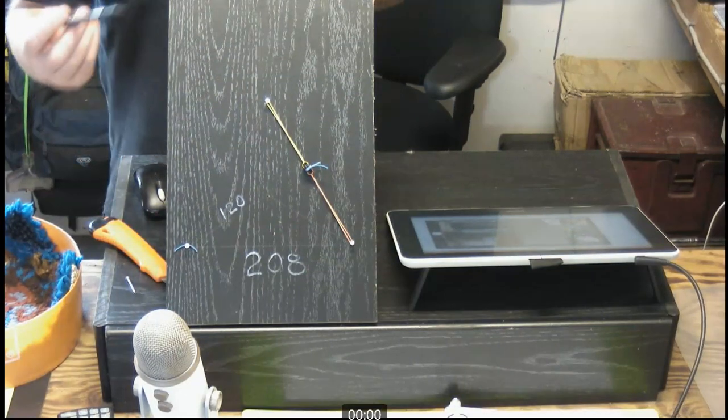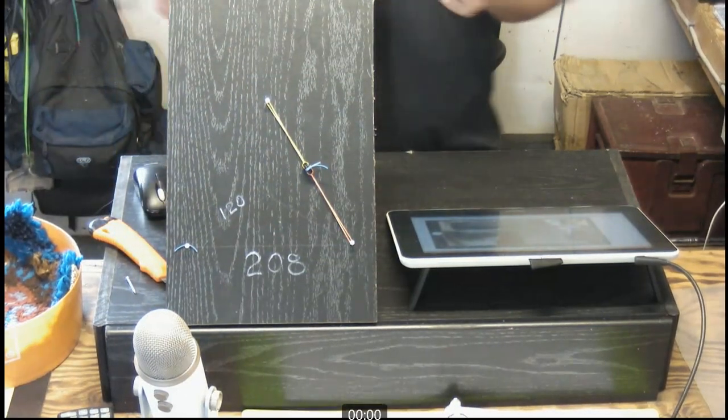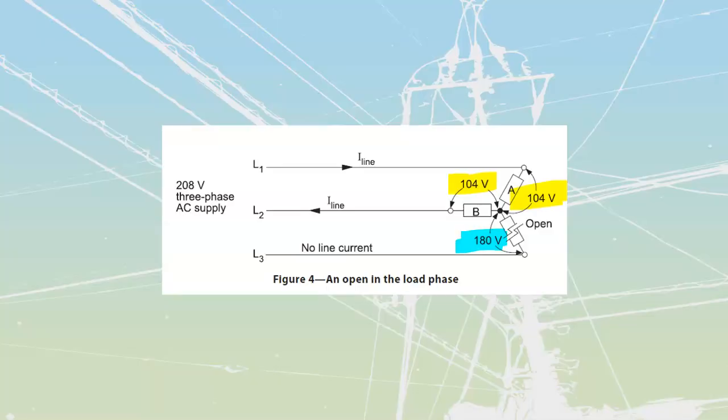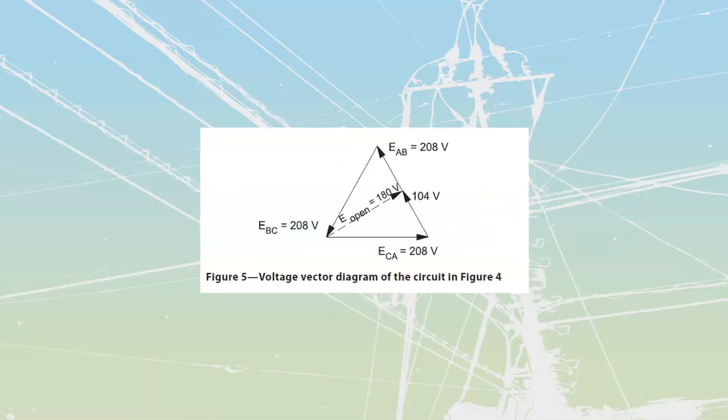And that value you're going to have left across here is going to be 180 volts at this point. Let's go back and take a look at that over here. Off of my pictures, we see that we have got this 180 volts. They show us the way that they summed that all up, the vectors over here. Remember how we said that, look, we're going to have one resistance across here, one resistance across here, across the existing lines. Therefore, we had the 208 that was divided in half, and so we just had this line over here, and really we're calculating this triangle.